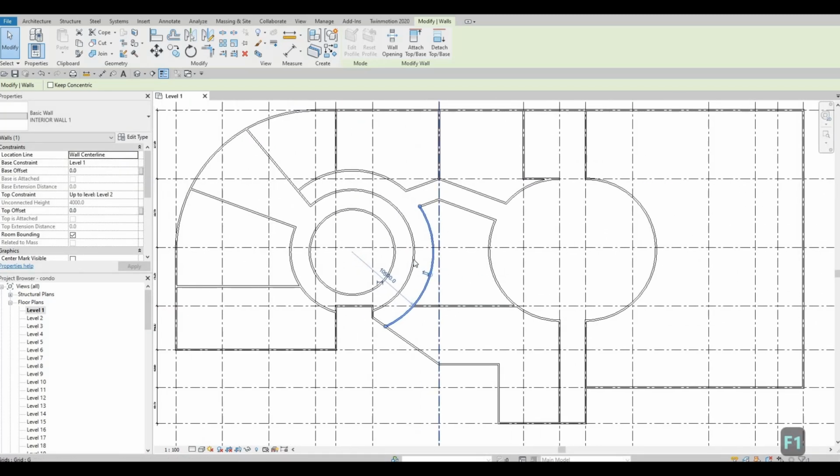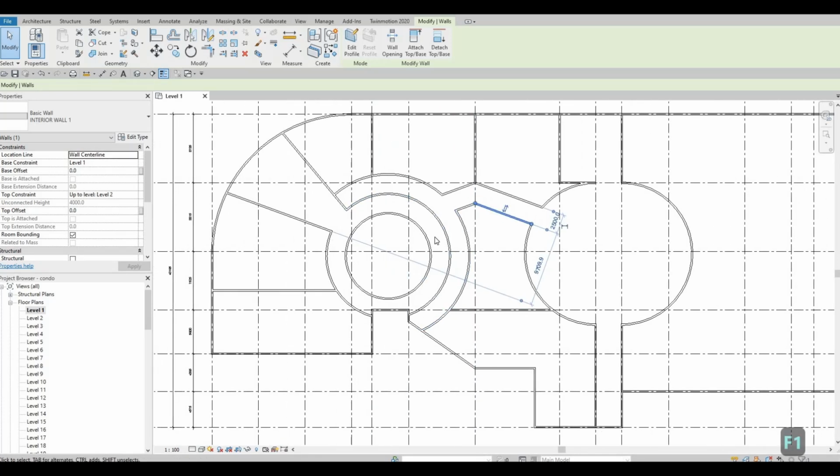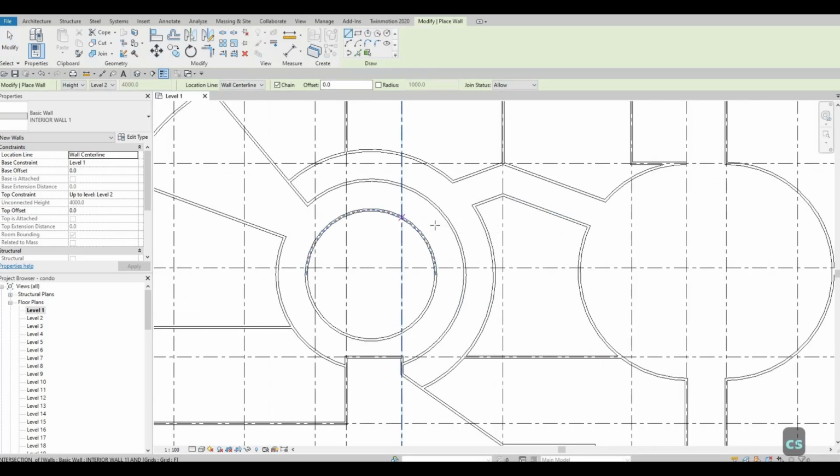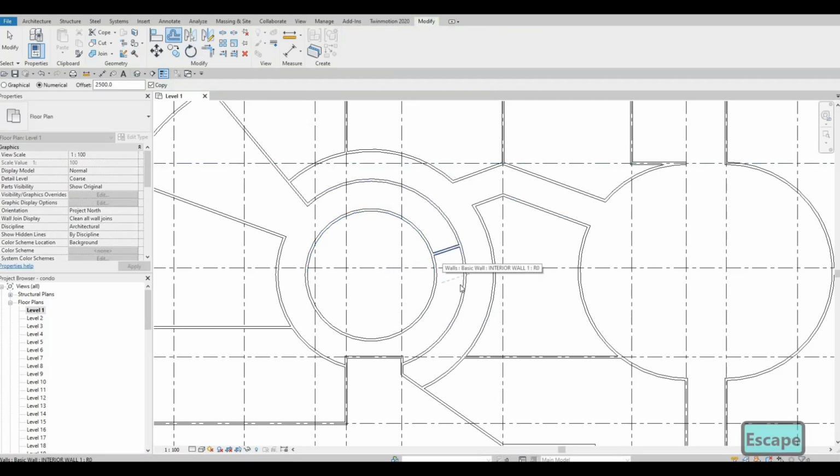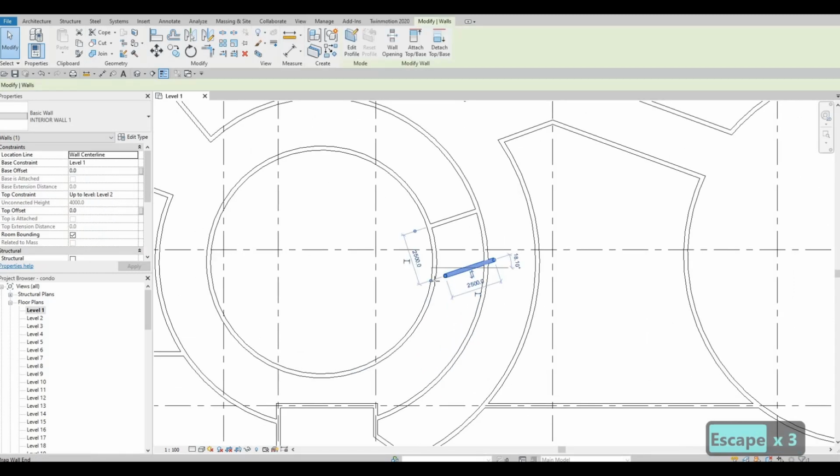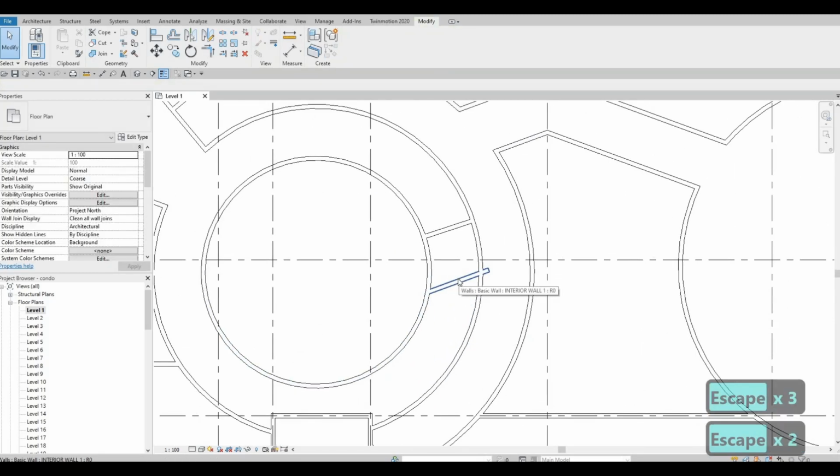So I'm just checking here. And then we need to add in an opening right here as well. So let's click the interior wall and then CS. Here we're going to add a wall right here. And we could just offset this with the same offset, 2500. And then with SL, that's split element, and then TR to trim and extend. And then we could just delete this.